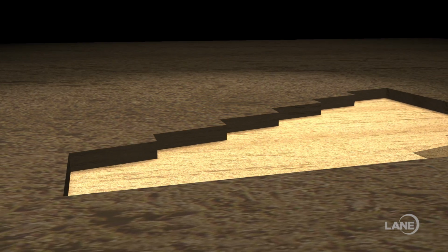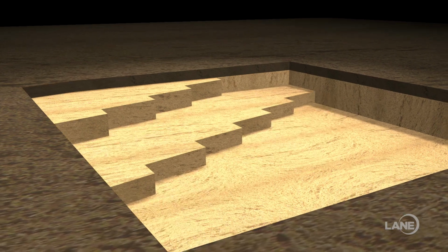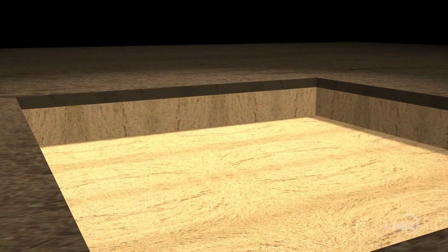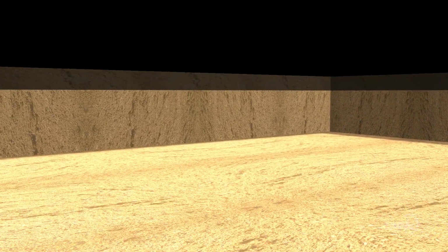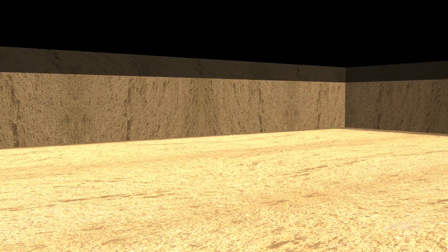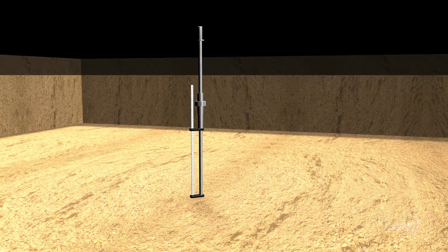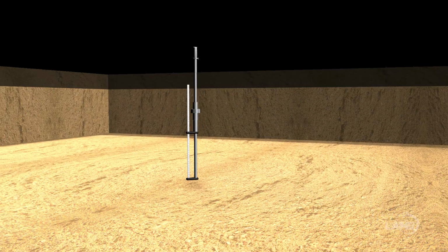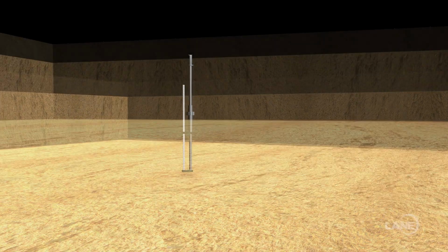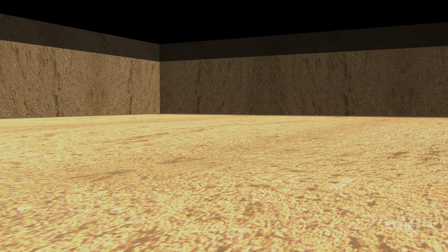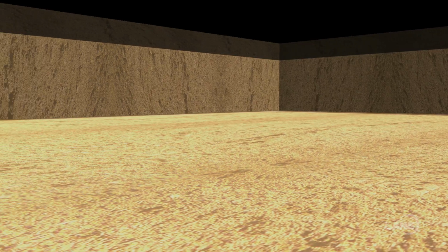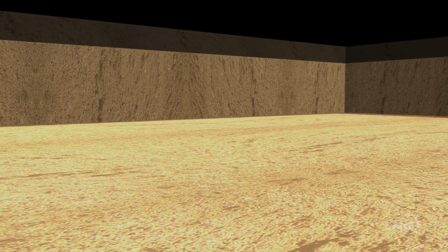Excavate the chamber system bed to the dimensions shown on the chamber system drawings. A flat, level, and firm subgrade is needed to support the chamber system. Once the bed is excavated, a geotechnical check should be conducted to verify the subgrade bearing capacity of the native soil. Cases where the subgrade bearing capacity is insufficient for the design chamber load will be addressed at this time.